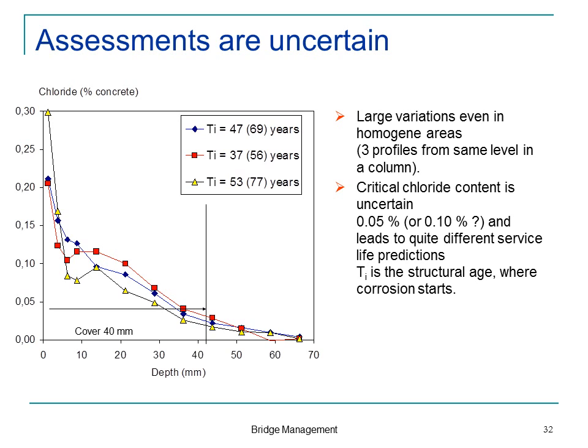Add to this that we are actually uncertain about how much chloride we need for the corrosion. Could it be 0.1%? Well, in that case we can add almost 20 years to the structure's age. This looks bad, but it's worse. Because remember, when we go out and inspect the bridge, it may be 30 or 37, 35 years old.